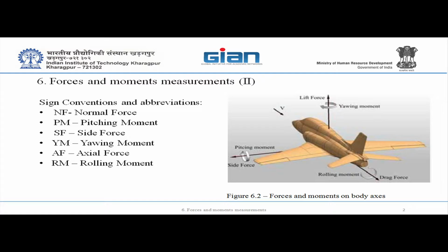What is important is that you keep your axes right. You're flying with X, Y to the right, and Z facing down. And according to this, you define your moments. Pitching moment is pitch up, and Y is to the right, and yaw moment is around Z, clockwise.